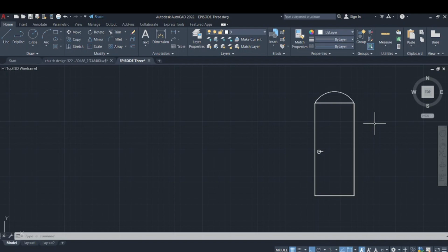So you should always know how to do that. You always have that at the back of your mind. Let's say if I highlight the whole of the drawing and I'm scaling it by 0.5, those places where I have 3000 will now be 1500. Those places where we have 2000 will now be 1000. Those places where we have 10,000 will now be 5000. So all the dimensions will be divided by 2. And if I'm scaling it up by 2, those places where we have 2000 will now be 4000, and so as the case may be.